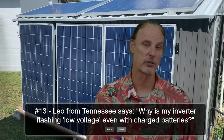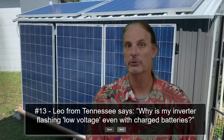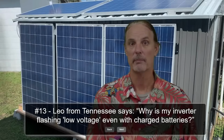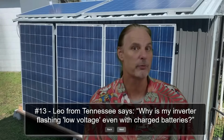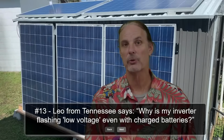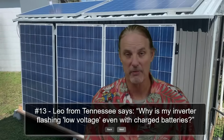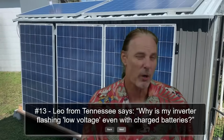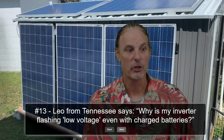Or are you looking at a state of charge that says you have 100%, but yet you've never run it down below 70%? And you don't bring it up high enough for it to balance, or you don't have an active balancer or a passive balancer, and you just have a battery cell that's being charged every night. These are all questions that you're going to need to ask before you say it shows low voltage.